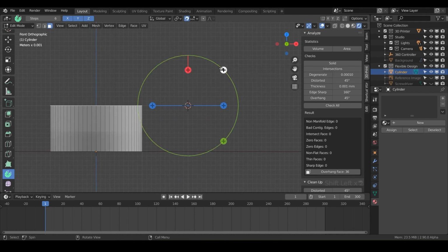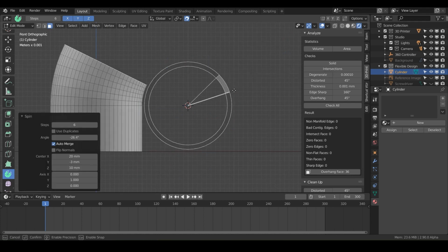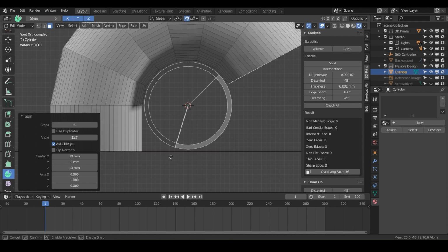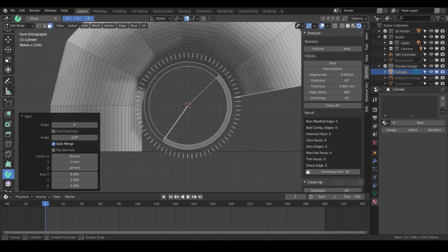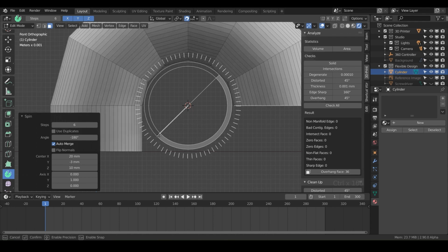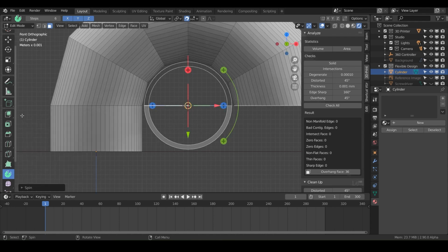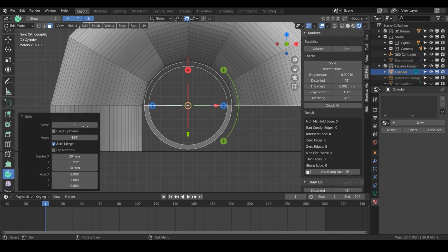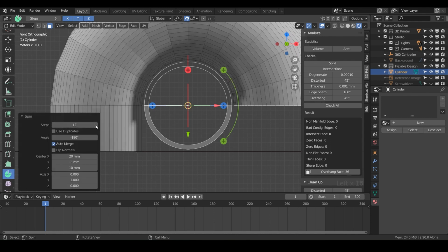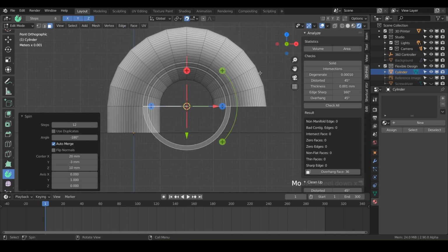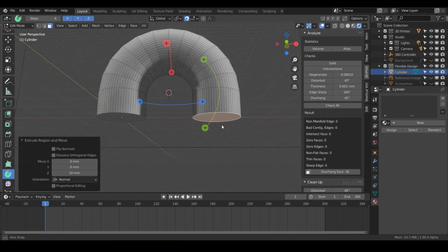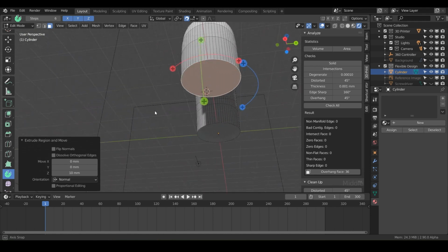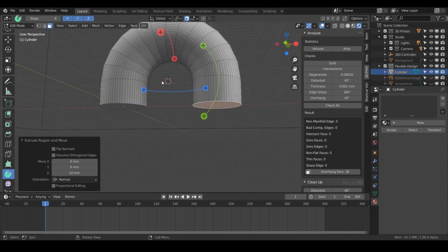Notice if we click on the Y here and click and drag, hey, we're getting some cool pipes here. And if I hold Control, it will snap incrementally. So there we go. Boop. And so that's 180. And then down here with the little box right here, we can twiddle that up and increase the segments. So maybe like 12, get a nice smooth curve right there. And then we can just hit E to extrude. And there we go. So we've made a really cool pipe just like that within a few seconds. And it's all based off of the 3D cursor.